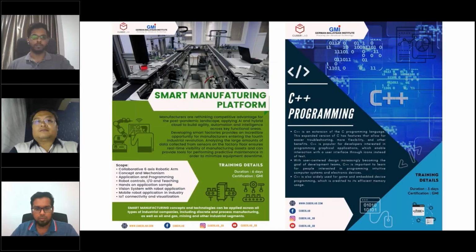And there are a lot of different brands in the market such as Cognex, Keyence, Halcon, SICK, almost any of the sensor brands have a vision system. It comes with a preset of tools which we can use, such as, like I mentioned, measurement, object recognition, all those things. As for the robots, they actually come as just a bare robot. One or two types of robots come with built-in vision, but those are very basic. So for most of the applications we do for customers, we always use external vision.